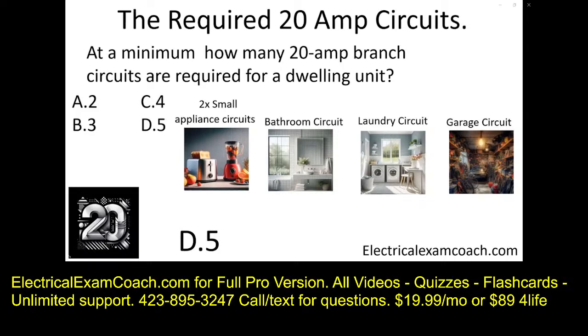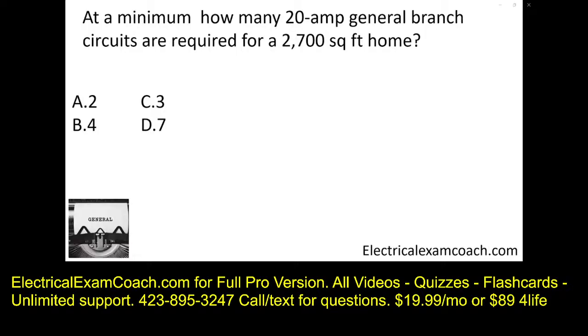Great job. At a minimum, how many 20 amp general branch circuits are required for a 2,700 square foot home? Now, your question may not say general. It may say for lighting and receptacles. You can keep an eye out for that. But usually if they give you the square feet, that's going to be the red flag for me that I'm calculating the general branch circuits. So how we're going to do this one, it's very simple. We're going to do it one step at a time.